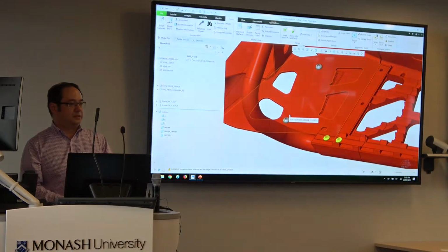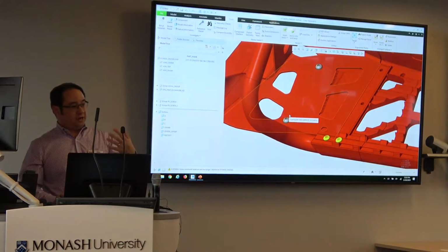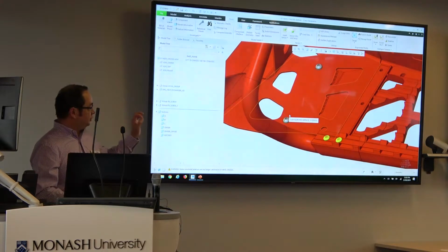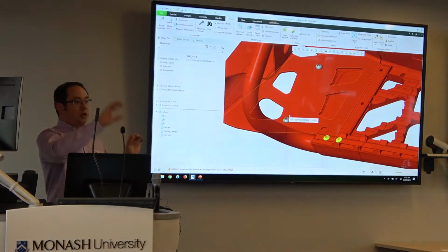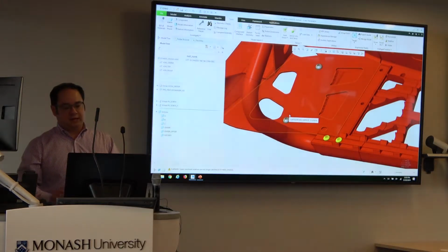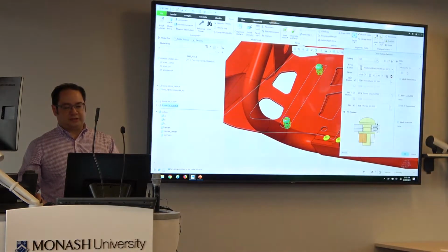Right. So IFX has been available since Creo 3. So any Creo user has IFX Lite. So you can do most of what I did there. In Lite, you can't do the patterning. It doesn't auto-detect the pattern and do it all for you. You'd have to go back later and manually pattern it. And also with IFX Lite, you can't customize the library.